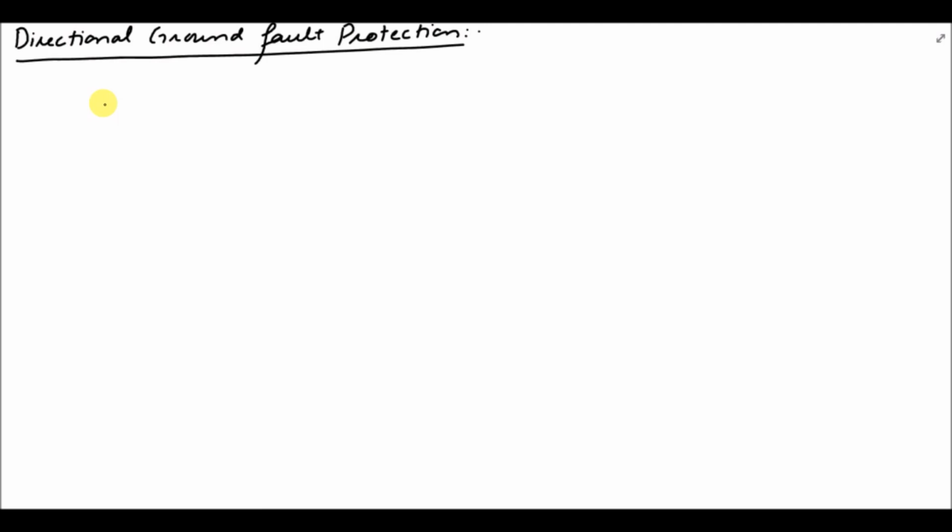In this lecture, we are going to talk about the directional ground fault protection. In the previous lectures, we have already covered the 30-degree and 90-degree connections. And we also talked about how we can decide about the ICC, which is the current coil current, and VPC, which is the potential coil voltage.